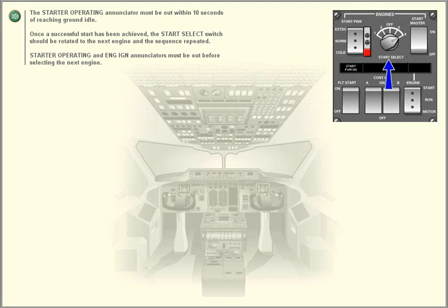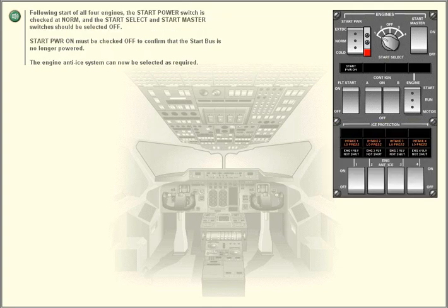Once a successful start has been achieved, the Start Select switch should be rotated to the next engine and the sequence repeated. Starter operating and engine ignition annunciators must be out before selecting the next engine.